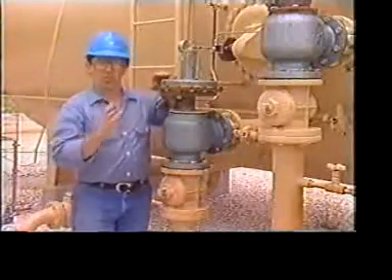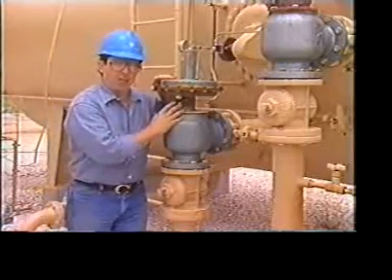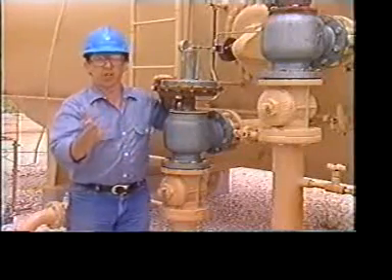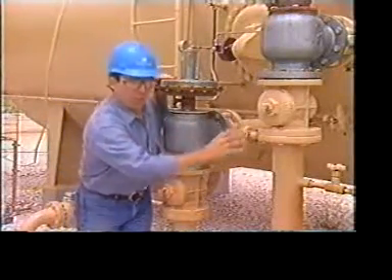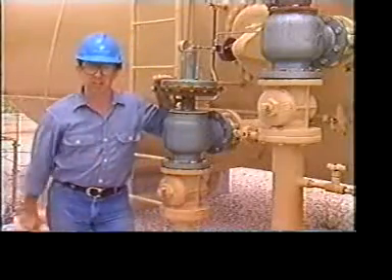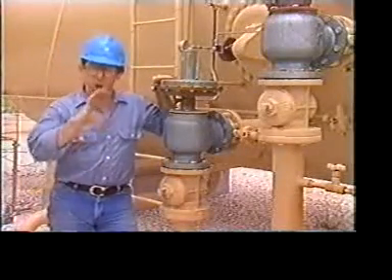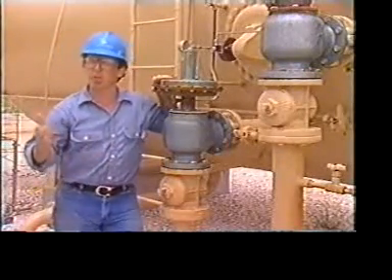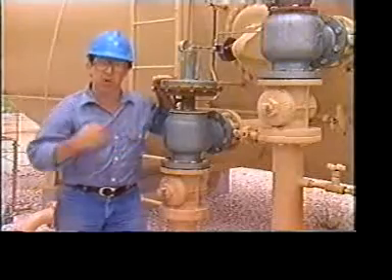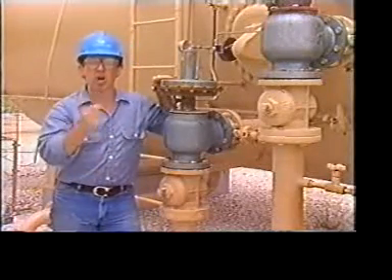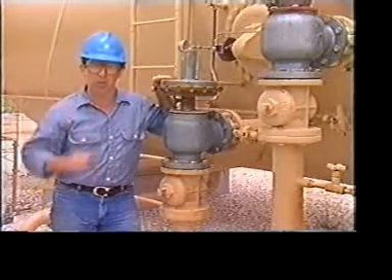If the water outlet lines are plugged or the water dump valves do not open, free water has nowhere else to go except out the oil outlet into the lease tank. If all valves are operating properly, the treater may not be able to handle the amount of free water produced, and a free water knockout unit should be installed upstream of the treater.